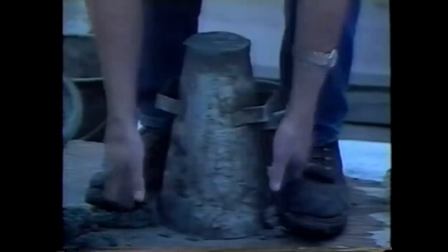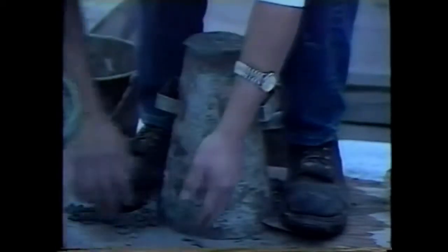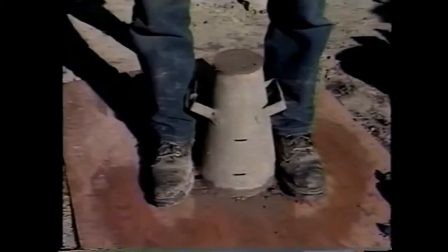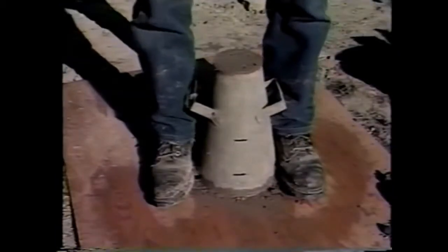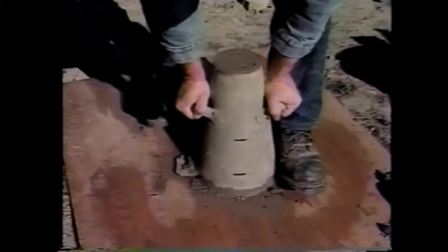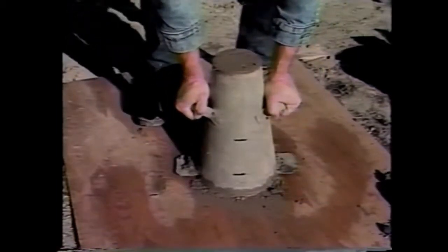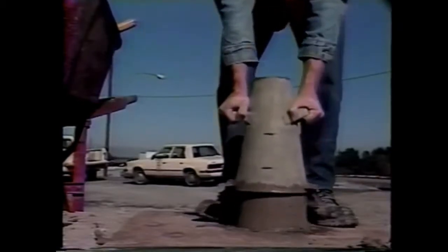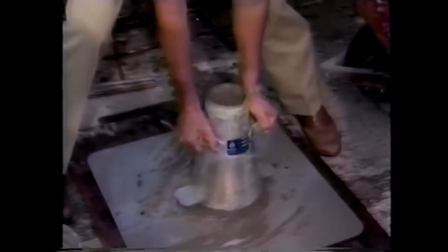However, the technician must be careful not to move the cone and disturb the concrete. Basically, both sides of the cone must be held still by pressure on either the handholds or footholds until the cone is removed. To remove the cone, both hands are placed on the handholds and downward pressure is applied to keep the cone stable before the feet are removed from the footholds. Now the cone is pulled straight up, slowly and steadily, without twisting or tilting. The removal should be completed in about 5 seconds. Slowly enough that the concrete doesn't pull on the cone.